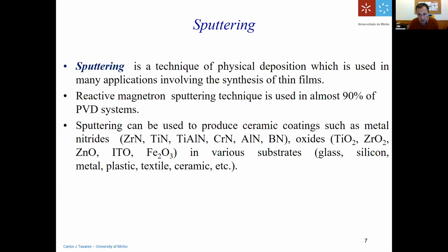On the base material, which normally is stainless steel or some kind of hard steel, you need to put a very thin coating, for example titanium nitride, titanium aluminum nitride, carbon, or chromium nitride, to enhance the mechanical properties in terms of resistance to wear.